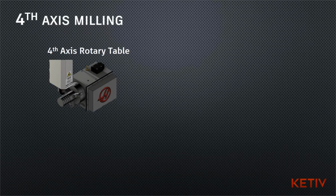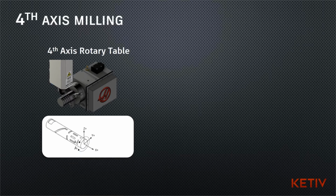So 4th-axis milling, this is your typical setup that you would see at a shop. You would have some sort of rotary table. The part is going to be the one that's rotating or spinning on the table. And while it's spinning, that's essentially when you get your 4th-axis, right? If you take a look at the diagram, we get a rotation about the x-axis, which in turn gives us a value in degrees. So you start off with your work coordinate, your initial position, and then you rotate some degrees in order to get to your next feature for your machine.